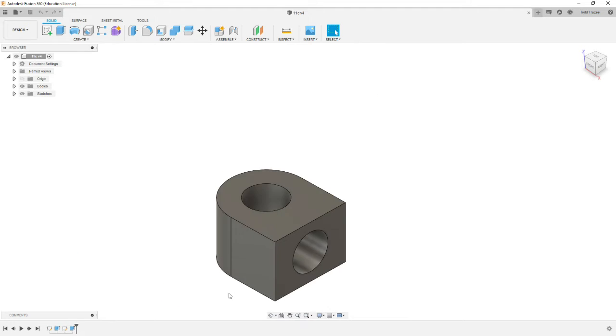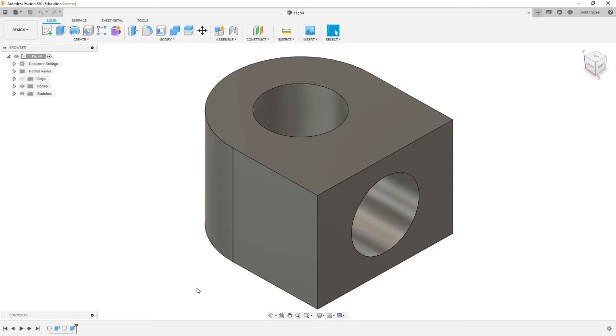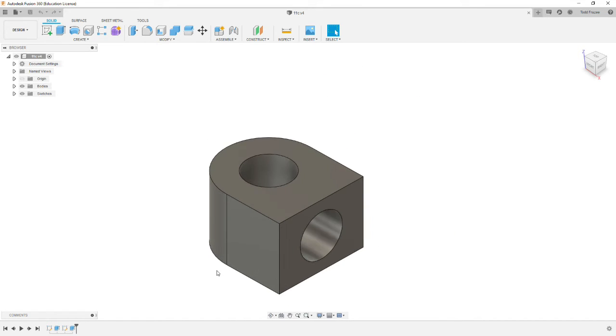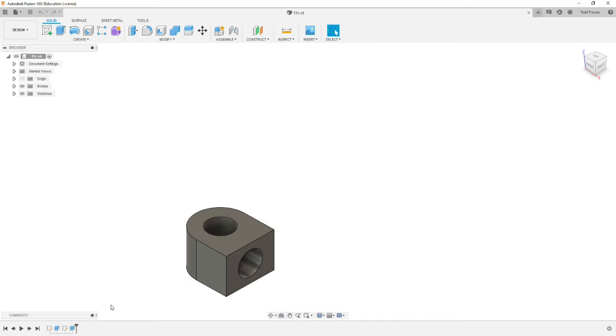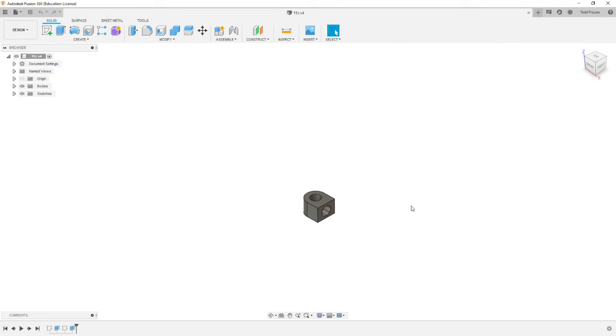Okay, moving on. For this particular part, it's very small and difficult to hold on to. Now you could try to saw cut a little chunk and square it up, but on a tiny part like this, and if you're not cutting a really high volume of them, it's common to use a rectangular or square bar stock, and you hold on to a piece of that stock with part of it hanging off the side of a vise. So that's the approach we're going to take on this, and in this video you're going to learn how to create stock based off a model body.